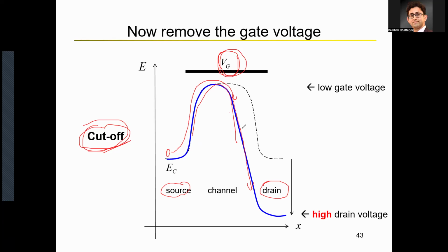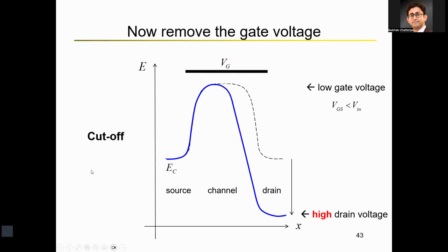However, there are things which are between zeros and ones. That's what analog circuit designers are interested in. That's what mostly we'll learn in the next few lectures. And then we'll also look at digital circuits using MOSFET. So we'll learn both in this course. All right. So if your gate to source voltage is lower than the threshold voltage required, then you are in the cutoff region.